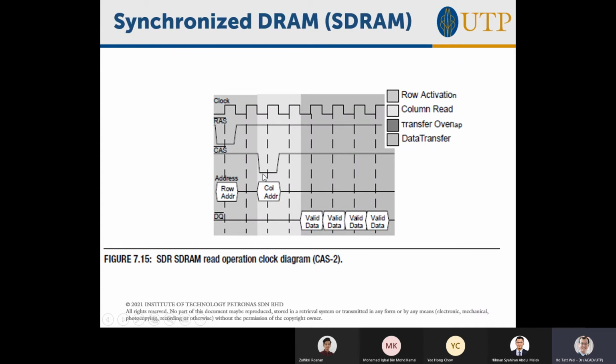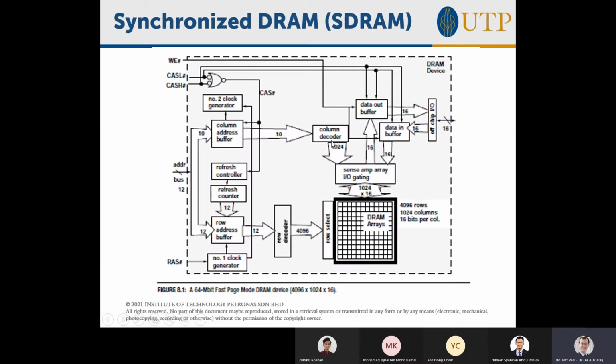Okay, so you put in the row address, the column address, then the clock, and at every clock edge after that, you get the first bit, the second bit, the third bit, the fourth bit within that row. You got this? This is the innovation of synchronous DRAM. They don't require you to update the column address or the row address, because internally they will store the column address. And when you're reading this out, there's an internal counter that will increment the column address and choose it. That's why we have these extra funny circuits here.